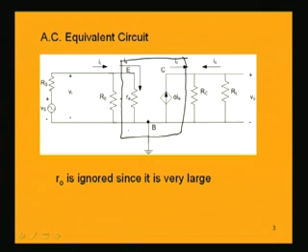Here we have the resistance re, the emitter base forward bias resistance, and the current flowing through re is the emitter current IE. Because it is a common base transistor, the base is grounded and common to both input and output circuits. The input at the emitter is the input current IE, and the collector current at the output is IC.